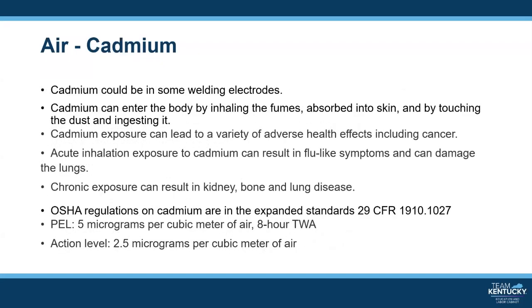Cadmium is another potential health hazard if it's used in some of the welding processes. Cadmium can be found in some welding electrodes and some brazing rods. This can be a combination of cadmium mixed with other metals such as copper or bronze. Occupational exposure to cadmium can lead to a variety of adverse health effects, including cancer.